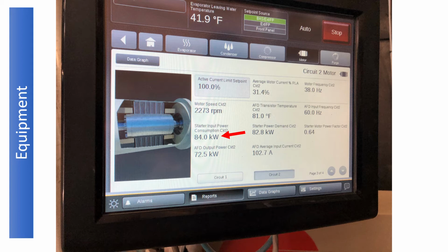It's going to run at way more than 84 kW, and circuit number 2 is going to come on. Actually, the other chiller is going to come on. But if this ran at 84 kW for 6 months, it would cost you $29,000. So that gives you some idea why we're paying such specific and careful attention to the way the chillers are controlled and the pumping system is controlled so that it can be run as efficiently as possible.